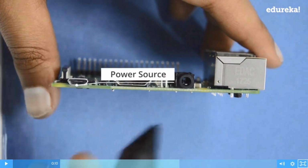As I told you, this is a micro USB slot where you can use, if you're using an Android or phone like that which supports a micro USB power input, the same thing can be used to power this. Only thing you need to make sure is that it needs to be a 1 ampere, 5 volts adapter. Some of the older smartphones come with power adapters which are of low capacity. They're 500 mAh or 700 mAh, so they run. But what happens is when you run for a little longer time, it consumes a little more power. It sort of hangs because the power supply is less. So better go for a 1 amp power adapter.